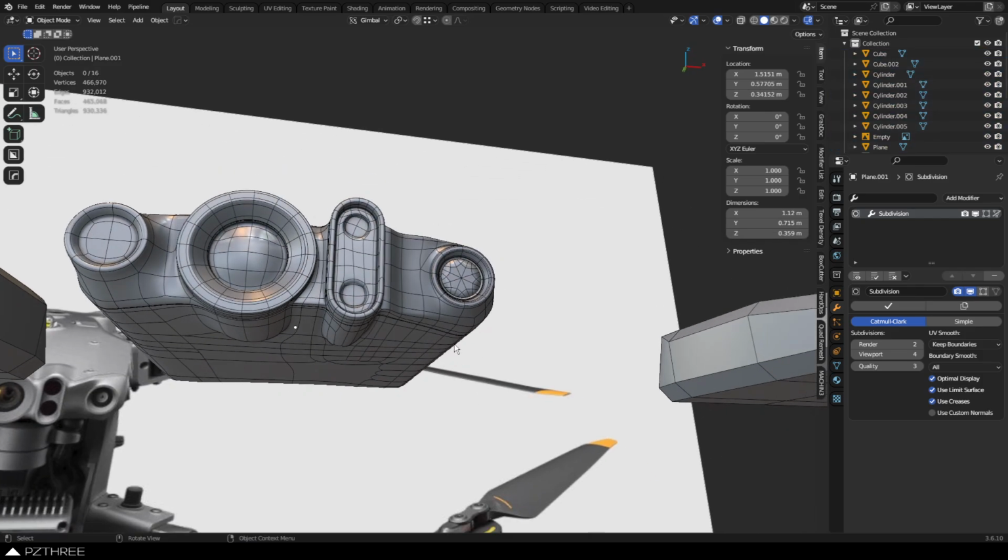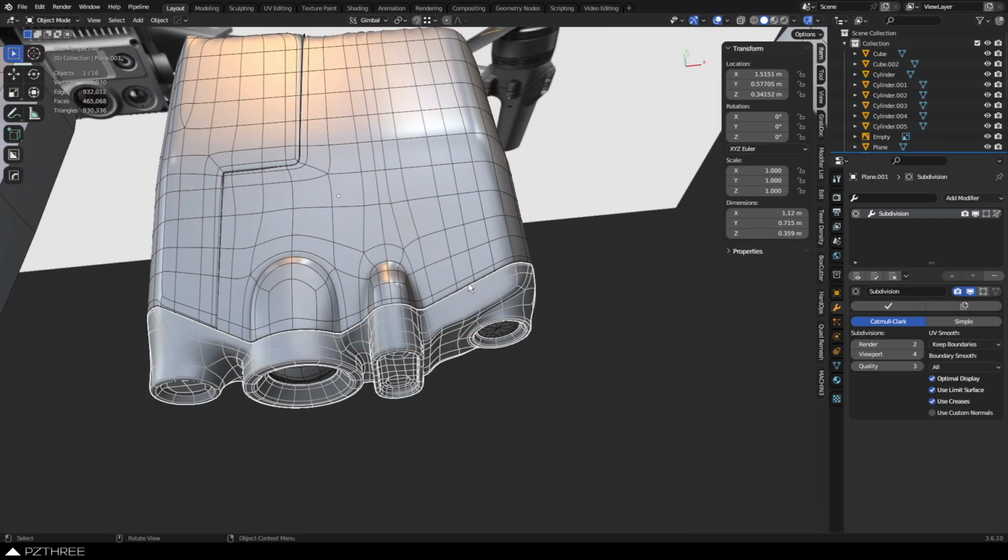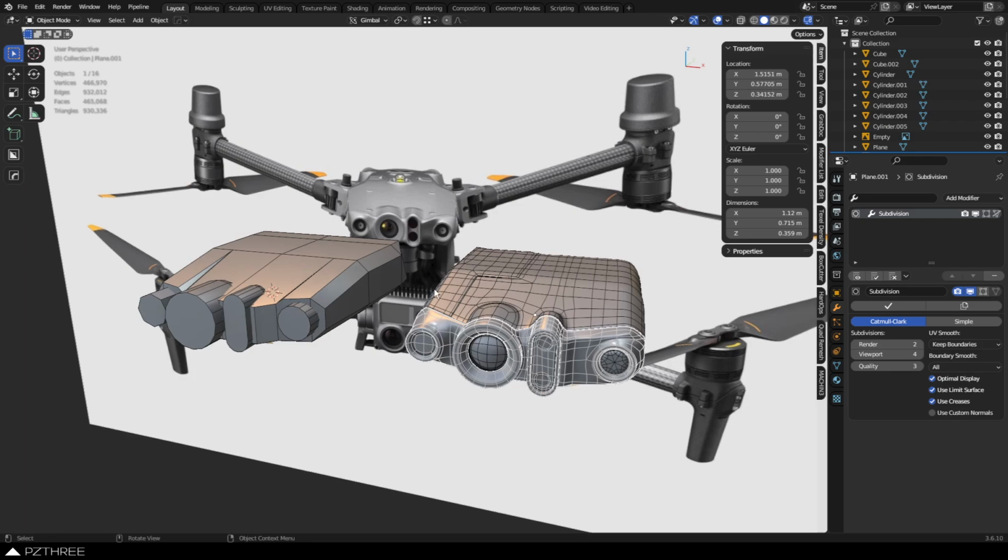Easier said than done. It's actually quite challenging, but you're going to ignore doing the breakup section at first, because there's a couple things to keep in mind. When this thing is actually manufactured, more than likely it's casted in a mold. So it's forcing plastic into a mold, basically hot plastic, and it cools down and pops out a little shell, more or less. That's going to be something like a 2-part mold. And this is something that happens a lot in manufacturing. That can play a role in how you go about creating things. You can approach creating things in little parts and sections as if it was going through a mold.